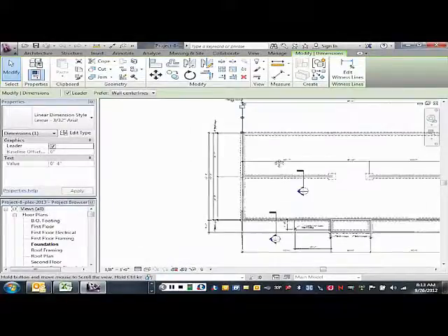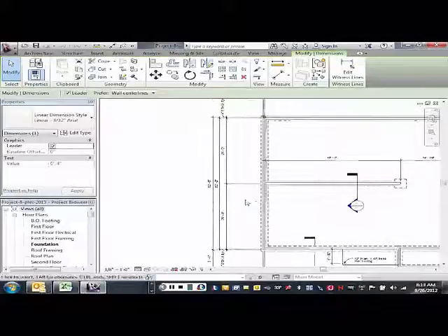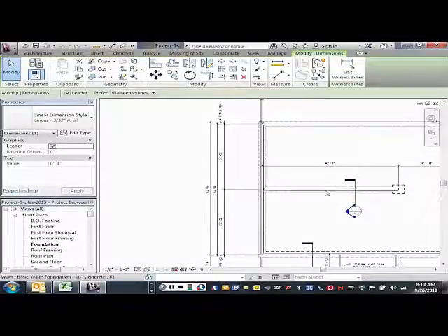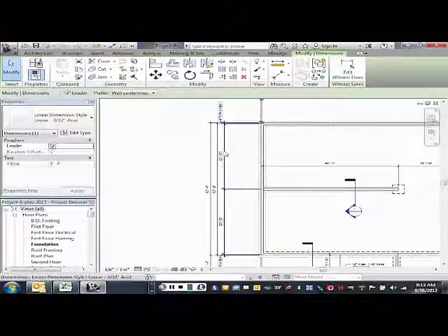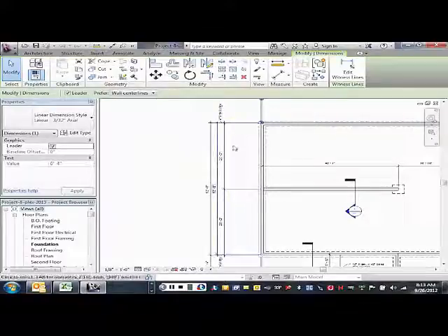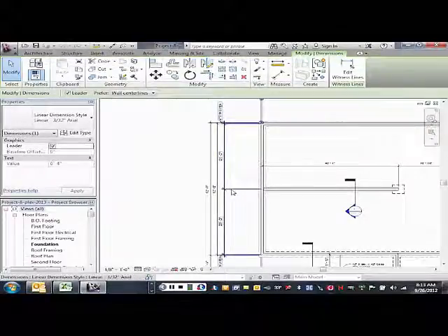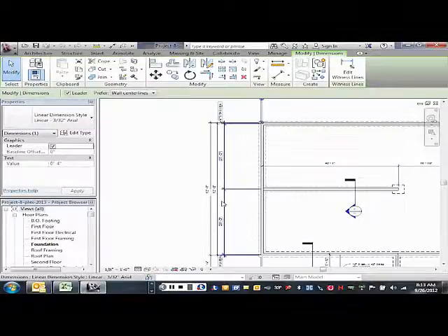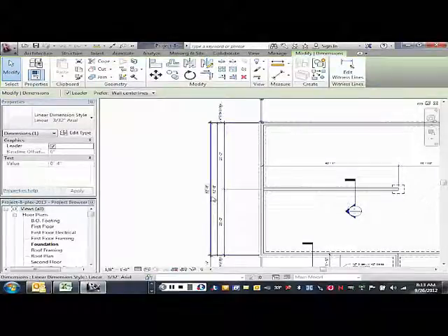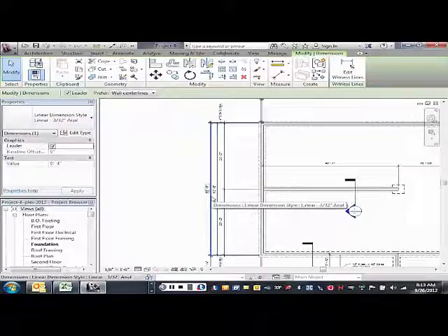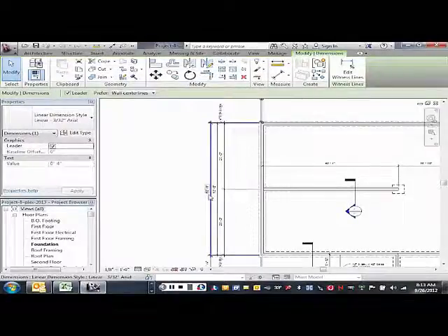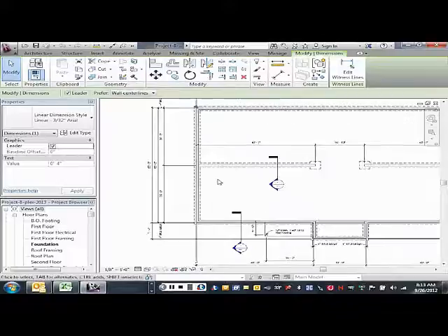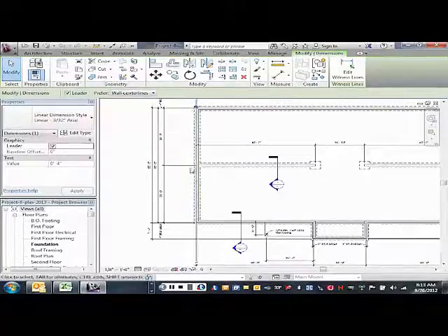Okay, so on the end of a building, again, we'll talk about dimensioning. We have this center bearing wall. So again, I dimensioned from the back of the brick ledge to the center of the center bearing to the back of the brick ledge should be 26 and 26. That should match up with your first floor. The overall of that should be 52 feet, and then another dimension to the overall of the entire outside of brick ledge should be 52.8.